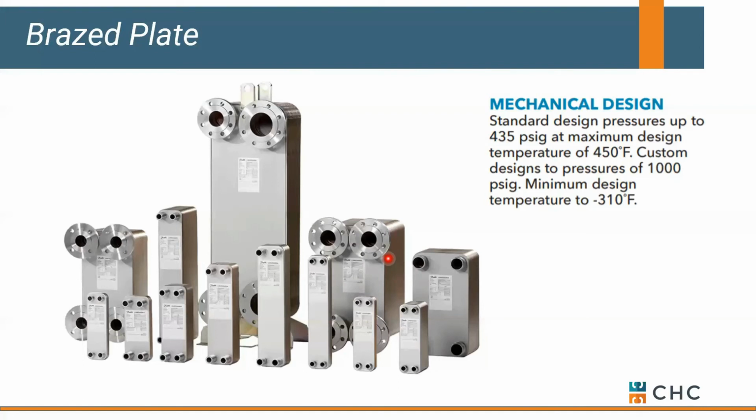Just make sure that you're protecting the heat exchanger, because if it fouls or plugs with debris, there's no easy way to open or service it. Okay, so that's where that max particle size really comes into play. You can also do this with refrigerant, light oil. There's a number of OEM applications going on. But yeah, a braze plate, certainly a lot of activity there. And with no gaskets required, I would say it opens up a lot of interesting applications.